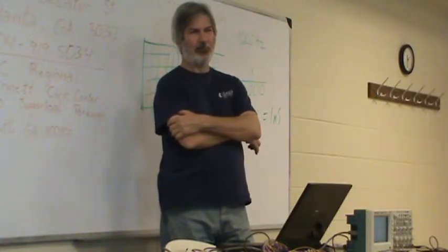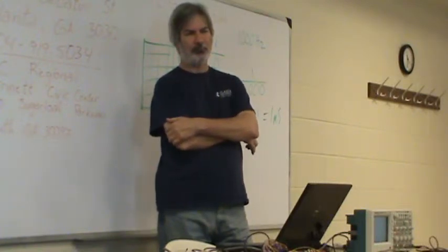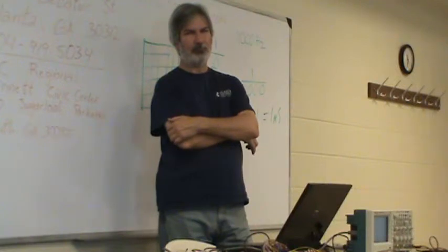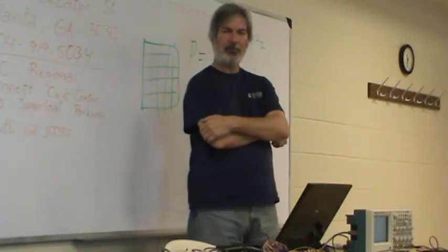Normal shows you nothing until it actually gets a trigger. There's no sweeping whatsoever until it sees a trigger, then it sweeps. Then it waits, another trigger, sweep. So it's like one shot, but it automatically resets. Okay, that makes sense, because I was never able to see a difference, but I always had my trigger set up, so that's probably why.